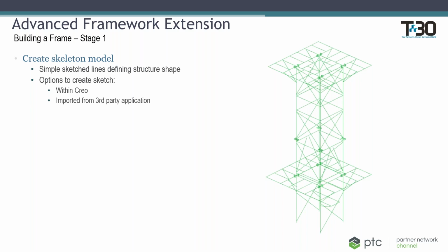It doesn't necessarily have to be a skeleton model, as you'll see in the demonstration, but it does definitely help when you're dealing with a large team to capture everything in the skeleton and then push those features down to your different teams. But the idea here is to capture the placement of your beams, the connecting parts, all within the sketch here, right?